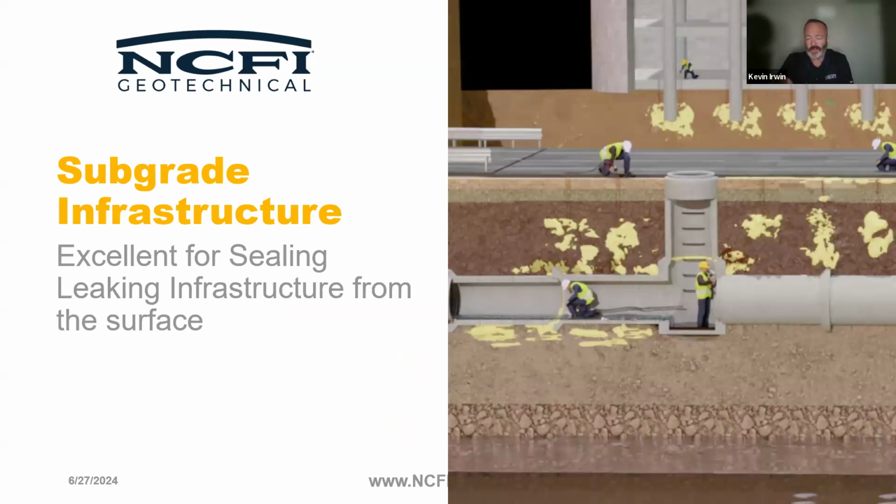And of course, subgrade infrastructure, injecting through a tube. Now, in a lot of cases, this is more water stop than soil densification, but the same chemical that we use to stabilize soils can also be used to stop water from entering a pipe, manhole, you name it.